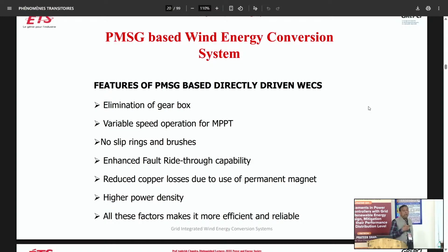Enercon has developed annular generator type PMSGs. They have the large diameter to accommodate even 100 poles or more than 100 poles. That depends on the capacity of the machine. So there is the advantage. If it is rotating with slow speed, it means very low wear and tear, so less maintenance, less losses. But I don't know about the cost. Perhaps it may cost more. That cost basically depends on how many machines you are ordering. If you are ordering 5 or 10 machines, the price may be different. If you order 100 machines, the price will be different. So it basically depends on this thing.